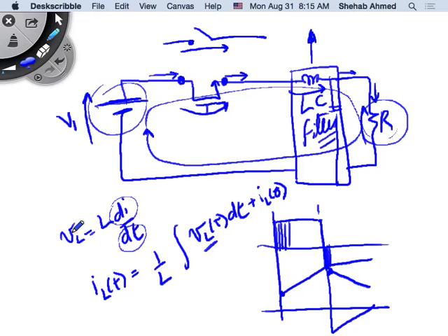Then when you open these contacts, the arc expanded, increased in length, so it decreased in power, because it's basically current flowing through an impedance. So they try to make the arc very huge, or the distance between the electrodes larger and larger, until they dissipate the energy that's in the inductor. So they dissipate it, the arc quenches now. Right? So that's what you saw.